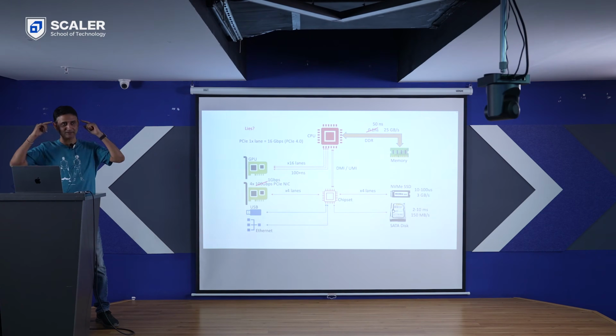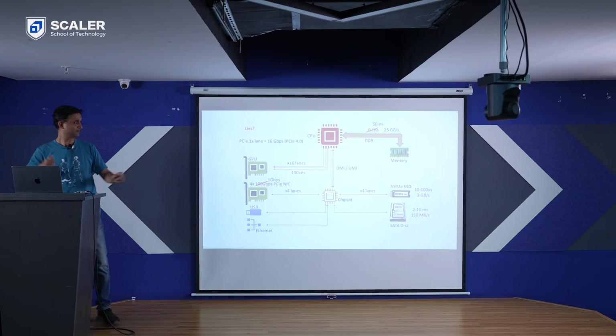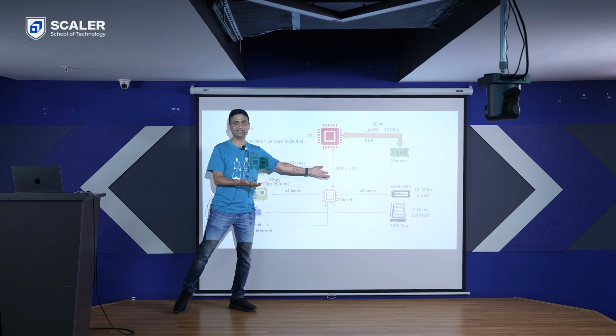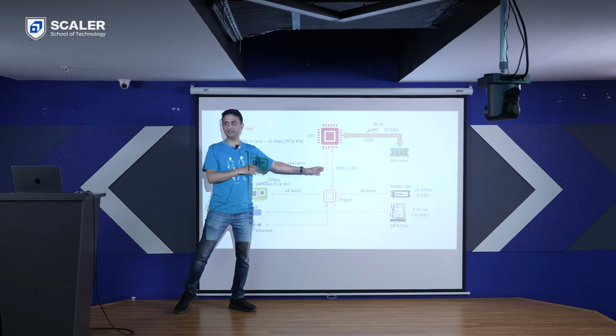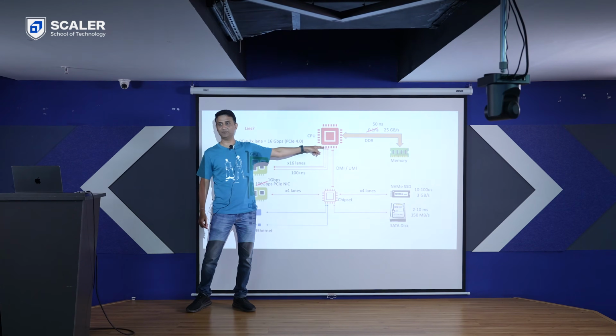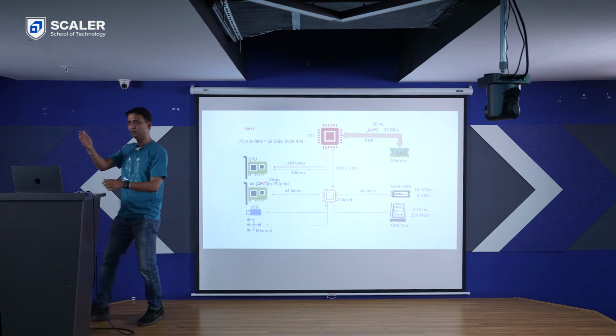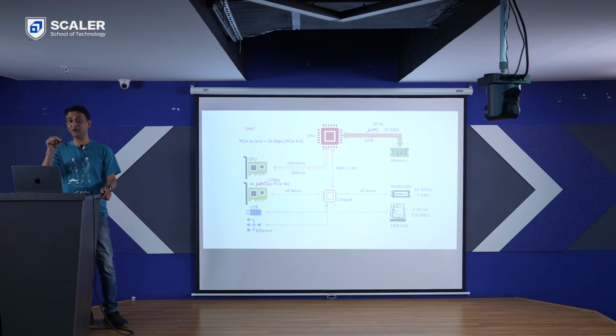Remember the principles? We want to ask questions. Is DMI part of, we talked about DMI lanes being electrically PCIe express. So when we talked about 8 lanes of DMI, is it in addition to the 20 lanes that the CPU was offering, or is it a part of it? Food for thought. And if you were to want to find out, how would you actually find out? Food for thought, not for immediate discussion.